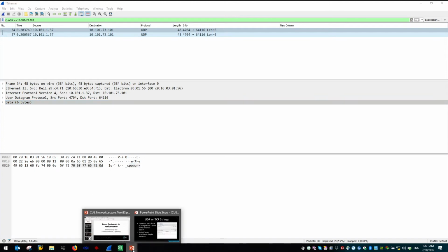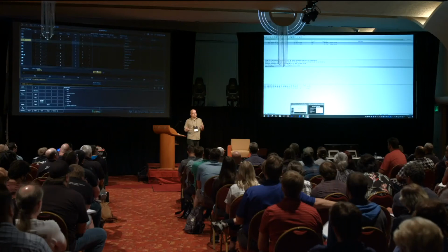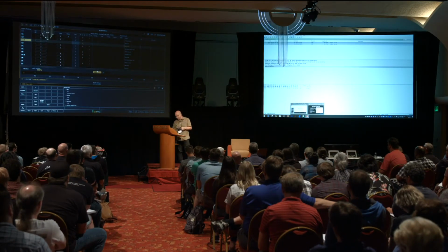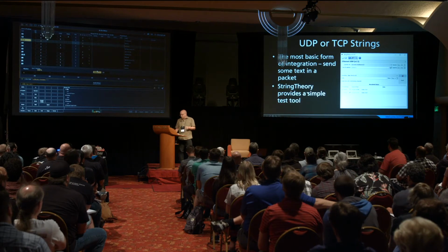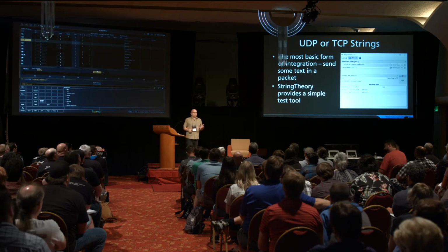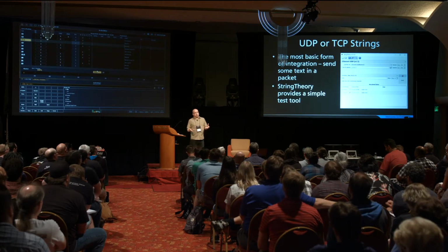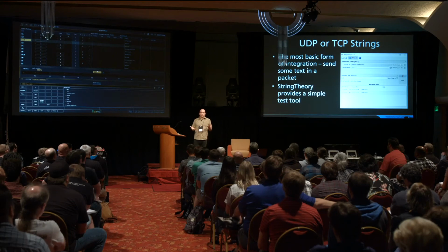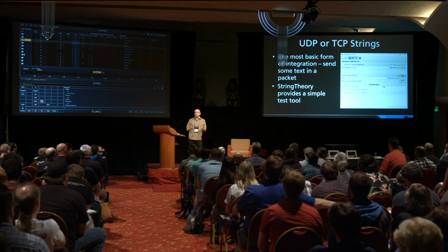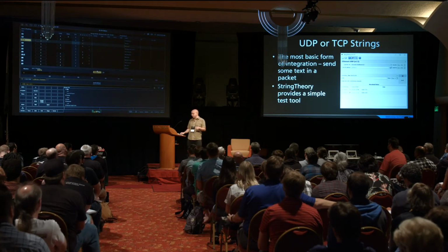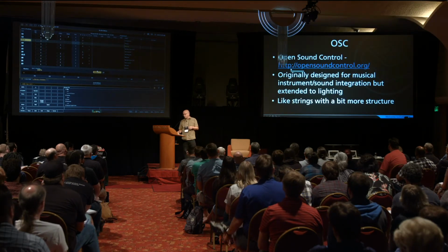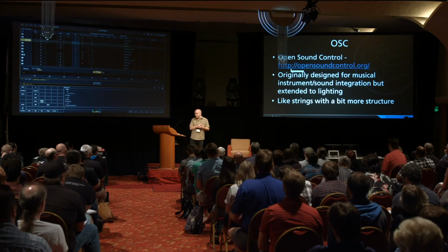So that's string theory. Useful little tool for testing out this kind of thing, available from the ETC Labs site. So UDP strings are good, but one of the problems with them is UDP means the unreliable datagram protocol. It might get there, it might not. Most of the time it's reliable enough for basic integration, but be a little cautious of using it for anything that's super show critical. So if you want something that's a better way of controlling things, you can use OSC,